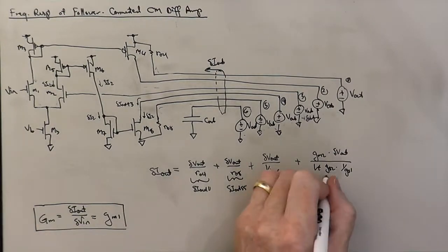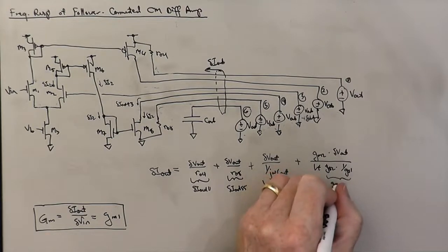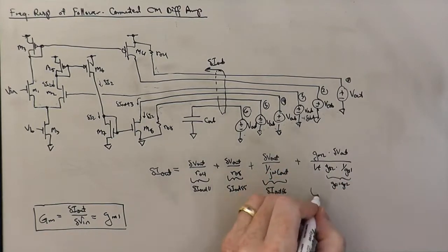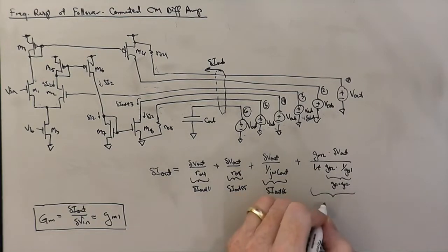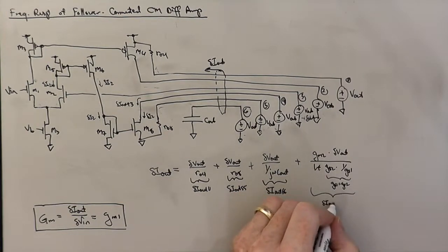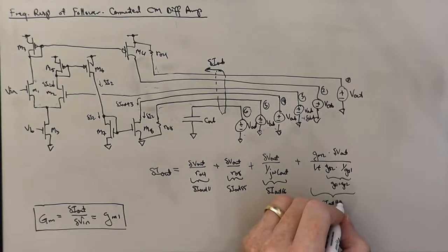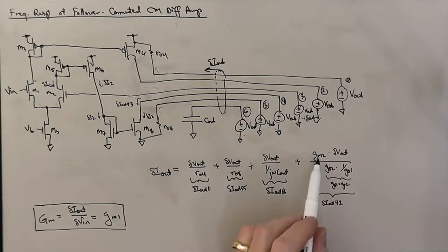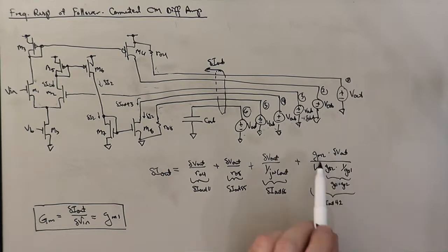And again, we have GS1 equals GS2 under the balance condition, and this whole thing is going to be delta I out in branch 4 due to replica source 2. And so this is just going to be GM2 divided by 1 plus 1, which is half of GM2.